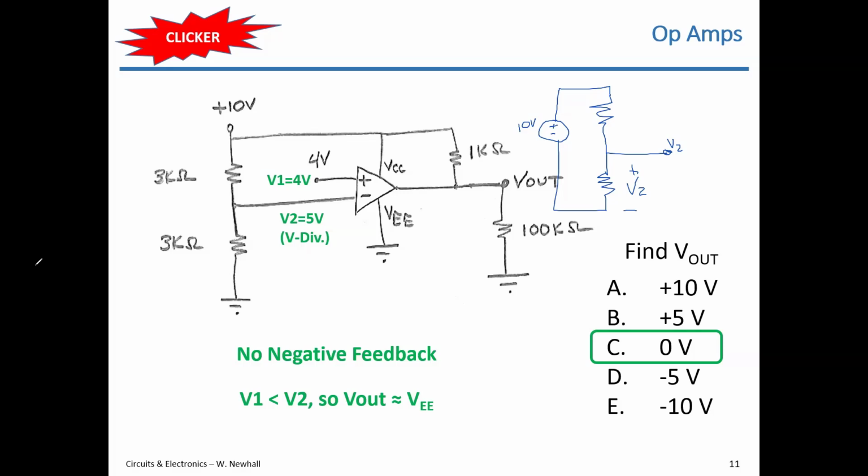All right. I have a quick question. Go ahead. Is it also a comparator since the top portion of it is constantly held at 10 volts, or is that just something not to consider? I mean, you could have a comparator that has different voltages for VCC compared to this 10 volts. Like you might have a different voltage across this voltage divider, and then you might have a different VCC value here that's not connected. It's a comparator because there is no negative feedback. And if there's no negative feedback in this class, it's a comparator. It's going to be comparing two voltages.